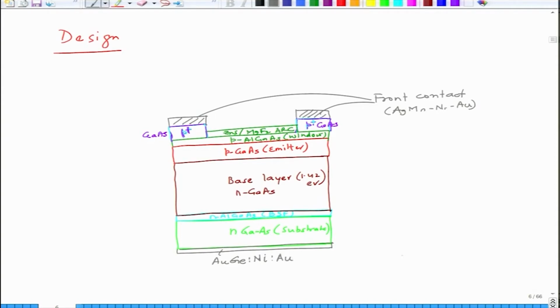So, you put in all these layers together so that you make a good contact. All right. So, again the work function matching has to be done so that carriers are not blocked by the electrodes, but again similar concept for the electrode. You can't cover the whole surface with the electrode because of the opaque nature of metal. So, as a result you have to optimize the electrode position just like you did in silicon.